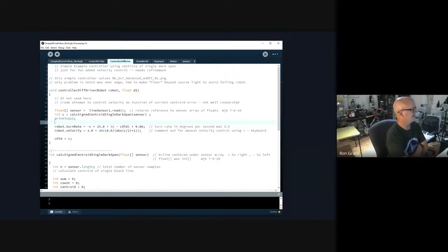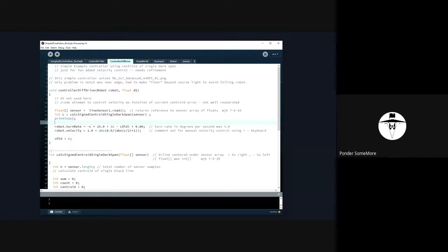Okay, so Will, could I ask: if we did put the line at the center line, do you feel like we could compensate with our PD controller? We could dampen it there. I don't think you can. It's kind of like placing it after the point at which you traveled past it. There's no way to recover that information. It just doesn't help. I don't think of it as a dampening function. I think of it as you are sampling forward in time from where your robot is going to be.